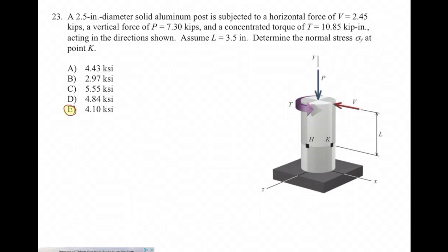Okay, without going further, can you tell me if there is any bending moment in that figure? There will be a bending moment, and that bending moment is caused by that shear force V. How much is that? That would be V times L. Which axis gets that moment? That would be about the z-axis. Should I take care of that when I'm determining stress at point K? Yes, because stress is not 0 for that point.